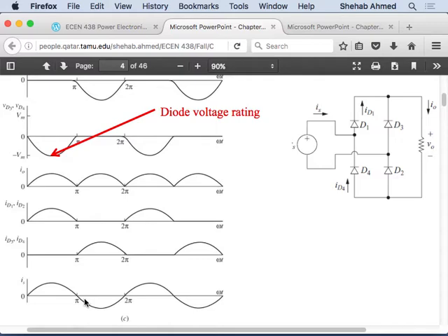Even though it's a simple circuit to create DC, it is not very useful, because typically you want to take this 240 volts, for example, and convert it to 9, 10, whatever you want to power up your electronics. And you need to step that down. So how do you step that down? You cannot use a half-wave rectifier in that case, easily. If you use a half-wave rectifier, then you cannot use a transformer. Transformers are a very nice, easy way to step down voltages and bring them down to a safe working condition, right?